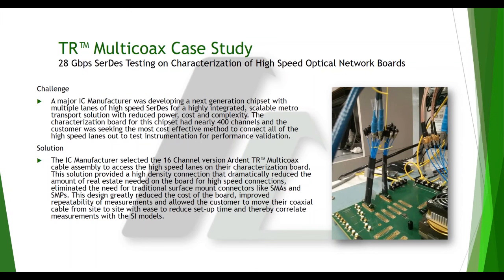So this particular guy had 400 channels that he had to measure. 400 channels is just impossible to lay out all those SMPs. So what happens if one of those SMPs floats or gets not soldered properly and you've got to rework the whole board? What happens if it's an important channel? And where are you going to put those 400? And if you put those 400 on there and you pay $10 each for them, you've got $4,000 in sunk costs on your printed circuit board.